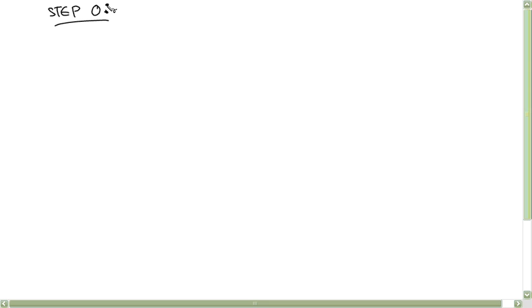So I'm going to call this step 0. That's a common strategy I employ to fix that. Find the reactions at the pin and roller. Okay? So draw that free body diagram, use the equilibrium equations, and solve those values. And when you're done, we'll do it back up here.